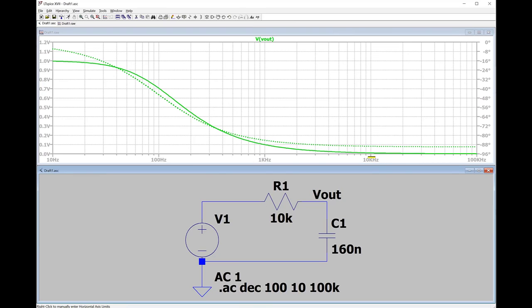And if you put in a 10 kilohertz waveform. So you put in a 1 volt times 10 kilohertz at 0 degrees, you'll get out almost nothing, a 0.005 maybe cosine of 10 kilohertz at about minus 90 degrees, minus 96 degrees. It's about minus 90 degrees, trust me. So we're often less concerned about the phase here and more concerned about the magnitude.